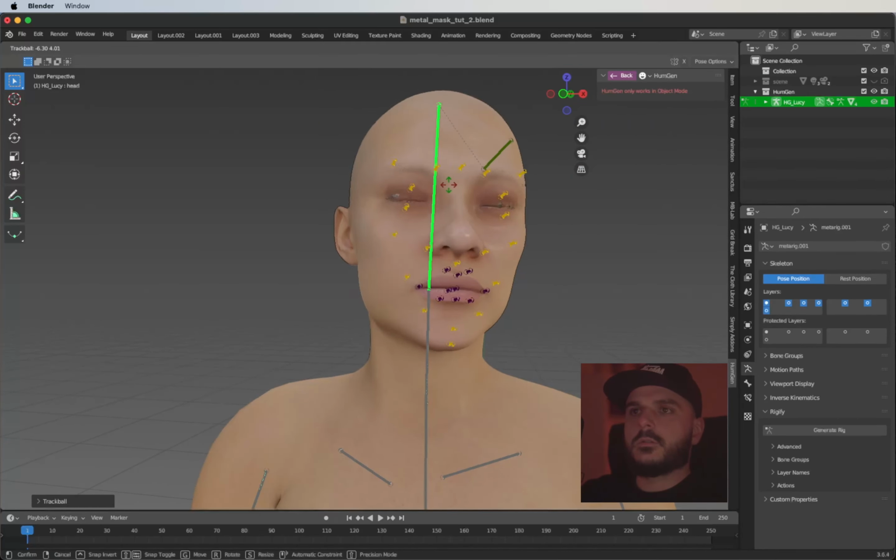Okay, now we are going to draw some curves on the face, and we are going to do that with a Bezier curve. So just hit Shift A, select curve and Bezier. Now you can tap into edit mode, hit A to select everything and X to delete it. Just delete the vertices. So we got an empty Bezier curve now.